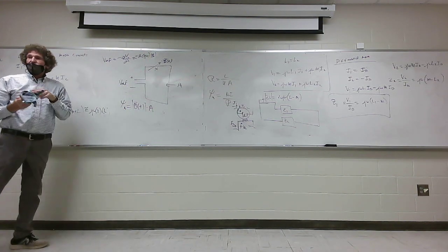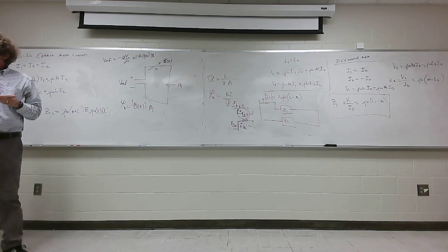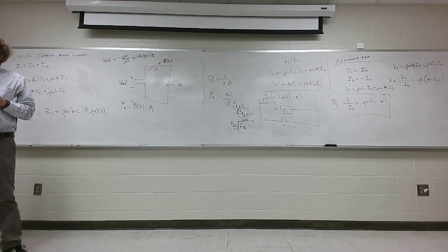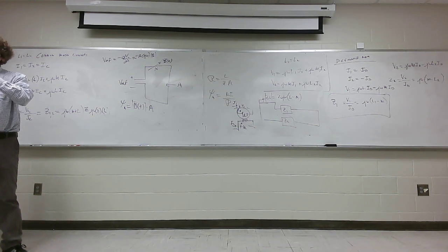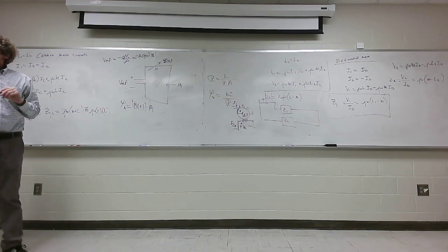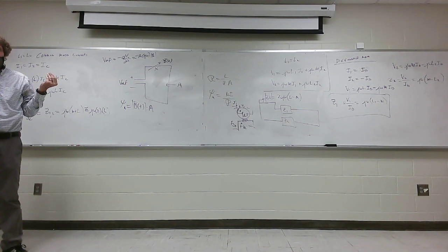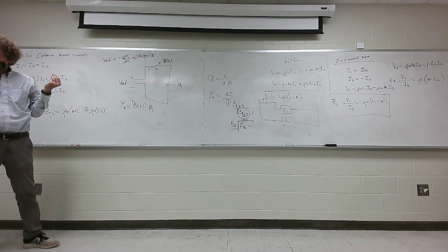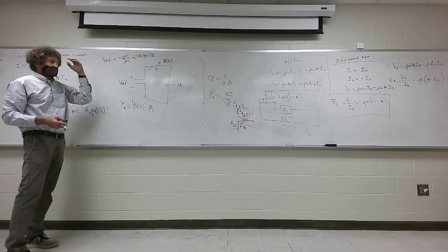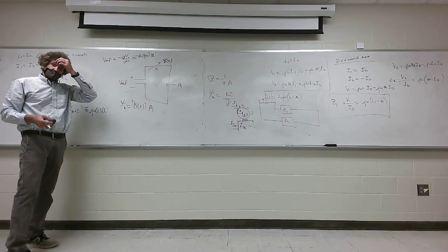In EMC, we do the calculation entirely. We estimate these things, and they're pretty darn close for a given situation. Now that's for one turn, all right? For one cable. That'll be the induced voltage. And if there's nothing to limit the current in there, but there usually is, then you could calculate the current by taking that induced voltage, dividing it by the impedance at that frequency.